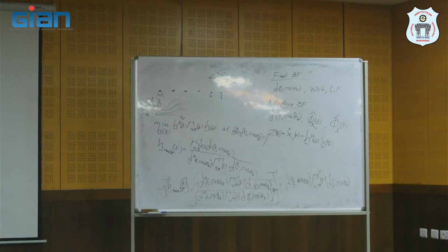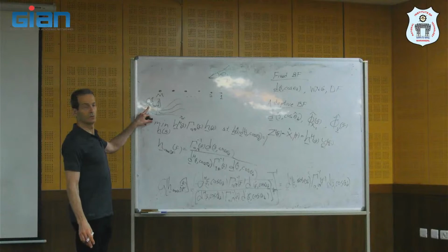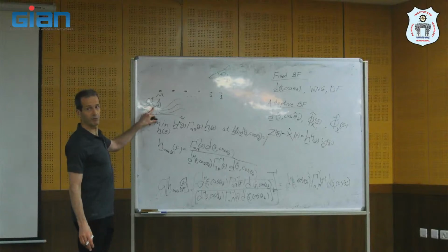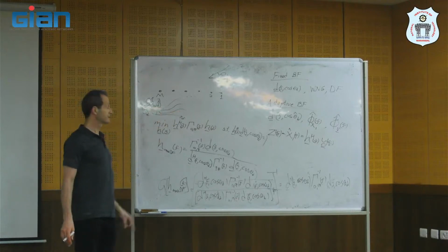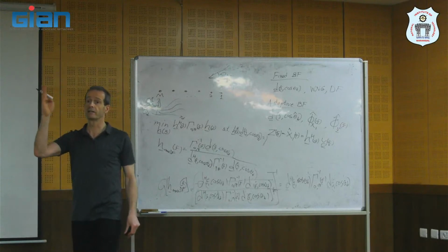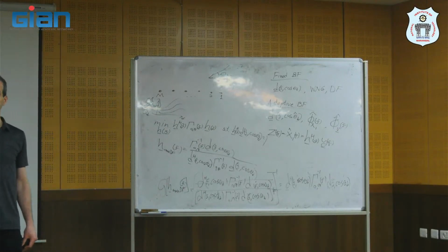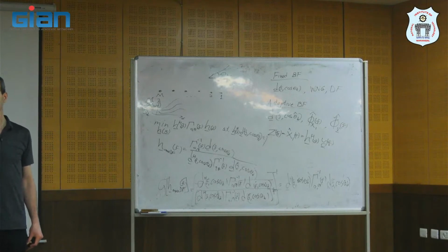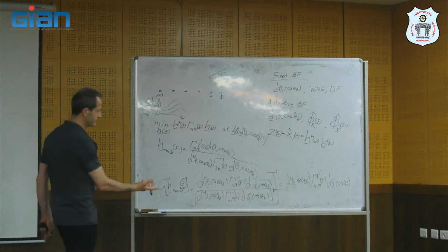Do you agree that this plot, how the directivity factor using the beamformer that maximizes the directivity factor behaves, depends on theta d, the direction where I look for the desired source? So it depends on the direction of the desired source. You agree, we obtained an explicit expression.